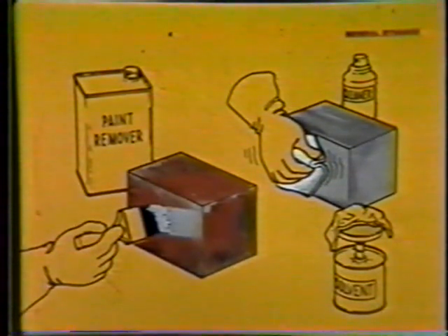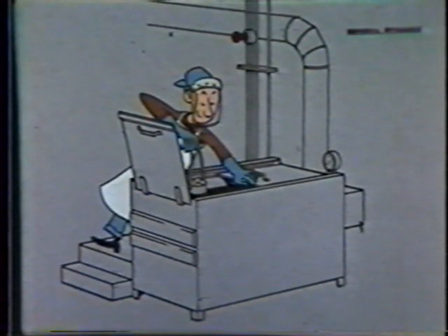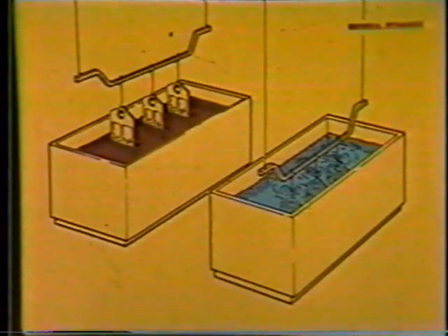Methods of application range from simple brush-on or wipe-on and wipe-off techniques to immersing specimens in solutions. Vapor degreasing, when it doesn't harm specimens, is especially effective in removing oily films and grease. The resultant heating helps drive off and evaporate moisture in discontinuities. Detergent cleaning is best for removing inorganic or solid soils. However, solutions used must be non-corrosive to specimens being cleaned, and following cleaning, a thorough rinsing and drying is necessary.